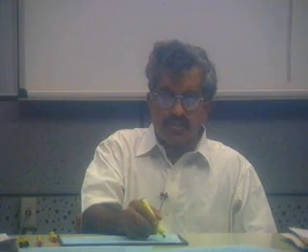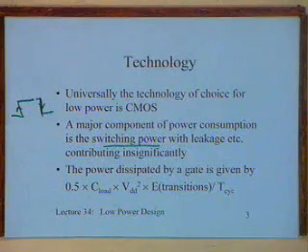The power is consumed only when the transitions take place. So at either the rising or falling edge, each transition results in some power consumption, because it essentially results in the capacitor at the output getting charged or discharged, and that is going to take some power.